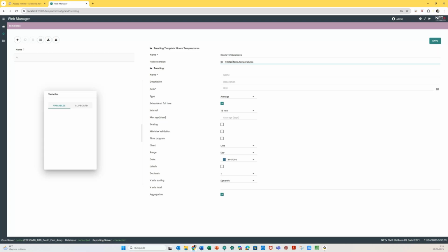And then, to create folders, one folder per room, I need to create a variable, because I have different floors and different rooms. So variables, for example, for the floor could be named this way: floor, inside keys, floor.